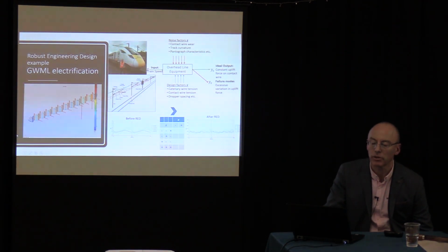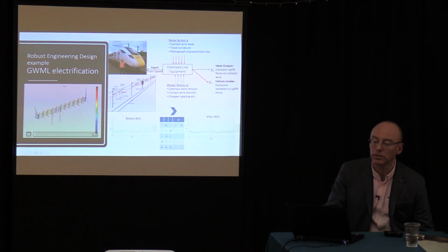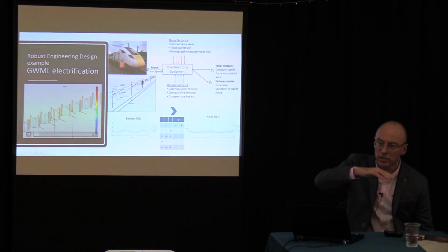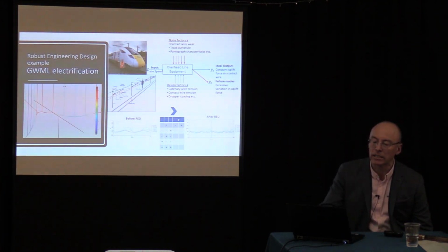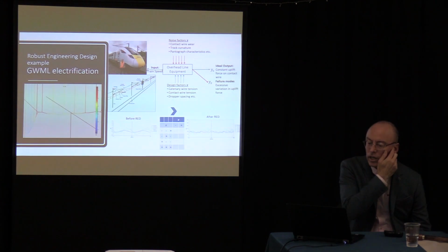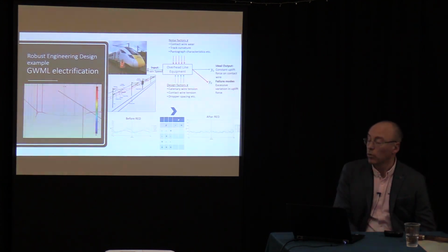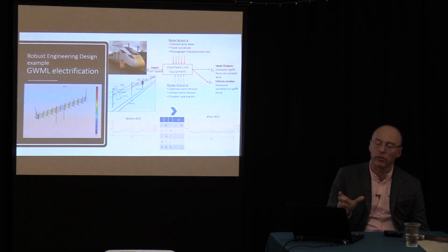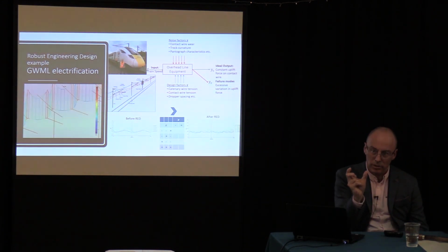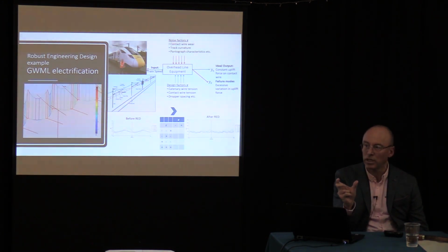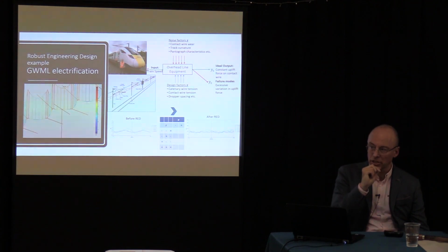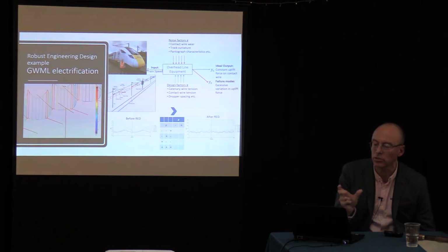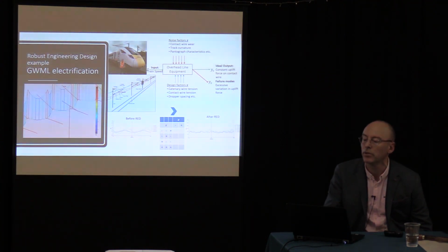So did it run through? I think it probably ran through already. Let's run it again. So this is a model of the pantograph, this structure here, and as it runs under the contact wire, it sets up an oscillation. And what you can do as an overhead line equipment engineer is specify what tension to put in the contact wire and in the catenary wire. Those are just two of the variables you can play around with.